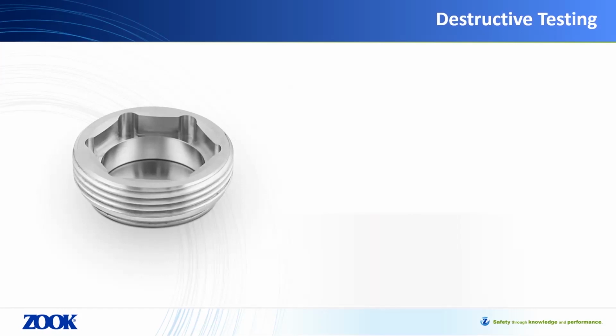All rupture discs, whether welded or not, undergo functional testing. Rupture discs are manufactured in a batch, and a number of random samples from that batch are selected to be burst intentionally to verify that each batch of the product performs as intended. While traditionally, the quantity standards of discs to be burst are set out by the major code requirements, being ASME and PED, additional burst testing data can be collected at customer request to even further confirm performance.